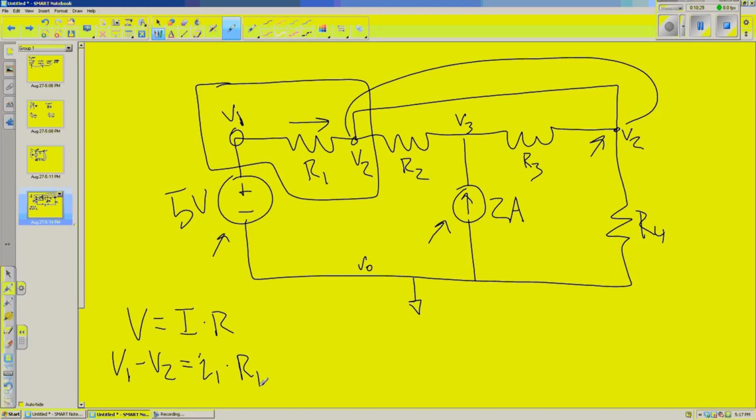So we've taken a differential, again that relative, and multiplied them, stuck them into our V equals IR, and voila, we can now start solving these. You get all of these nodes going, put up equations for each of them, and eventually you'll have enough equations to solve for each of the variables.